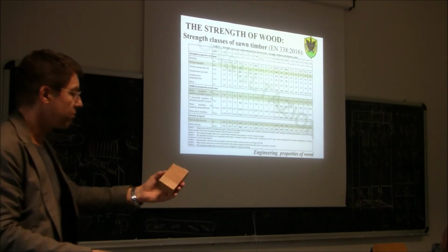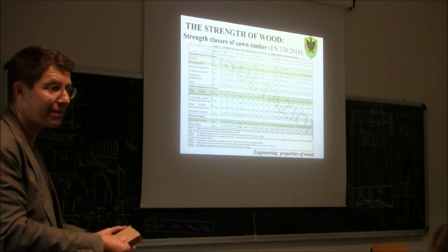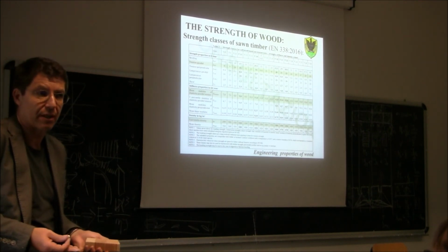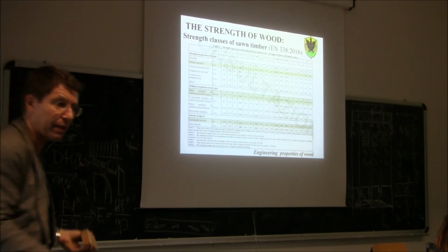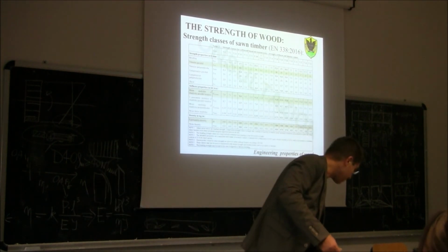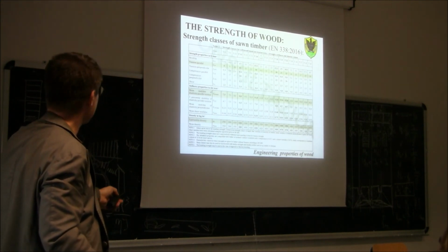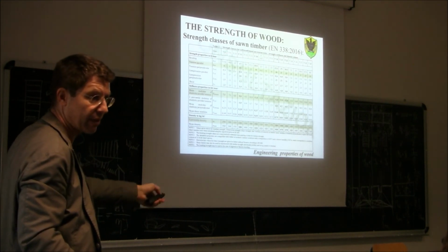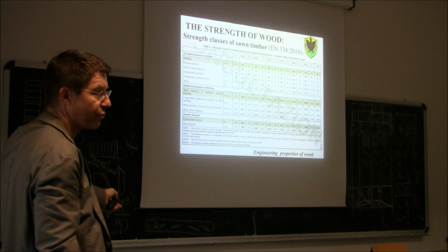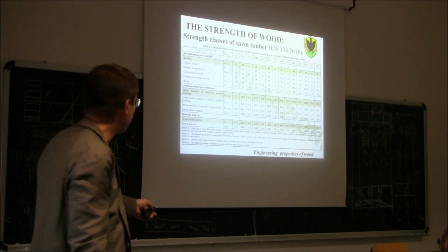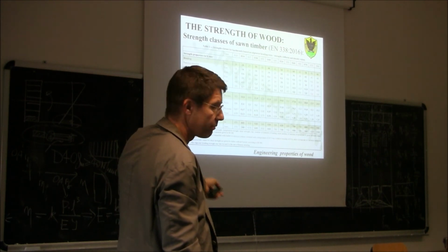So when it comes to making a glue laminated cross section, it's better to know the actual tensile strength of the plank rather than the bending strength, because in the end, the plank is mostly going to work in tension in the cross section rather than bending. Is it clear? So for this reason, for the planks we mostly use these tensile classes here, T10, T11, and so on. Those are the classes for the deciduous trees, we said before, for hardwood. You see there is much higher strength here, you can get up to a huge value.